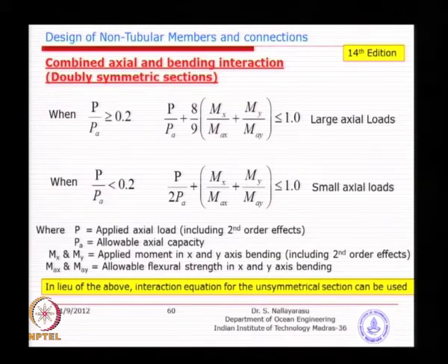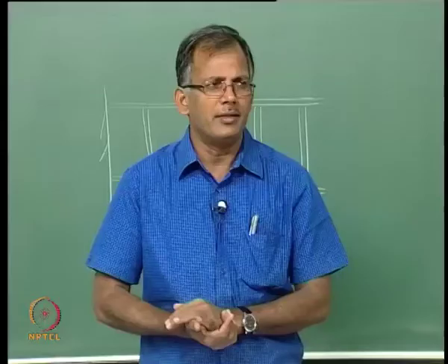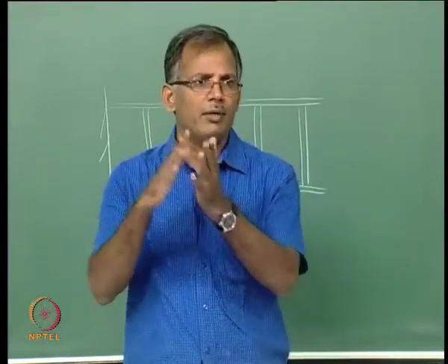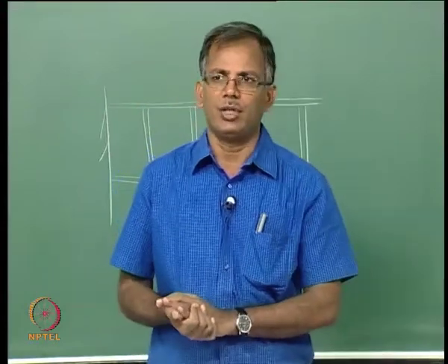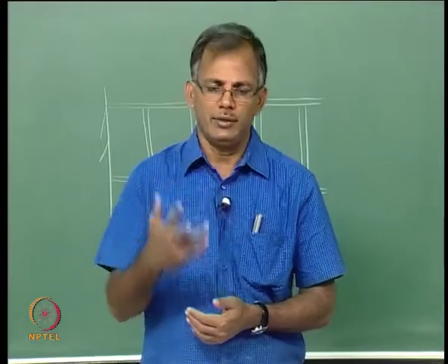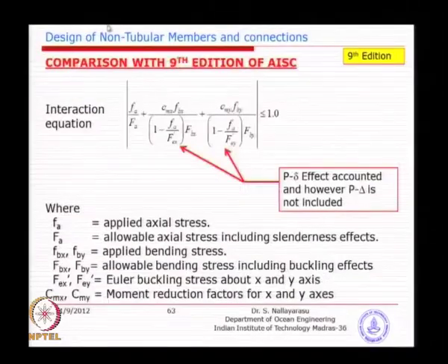And again here we have two subclasses. One is when the load is axial predominant, then you have this formula. When axial is slightly smaller, less than 20%, then you can use the second segment. Similarly, like we had in API, when the fa by Fa is less than 0.15, you have a set of formulas which is slightly modified, and when the stress is predominantly axial, then you have an interaction formula, something like this. This is for the buckling case.